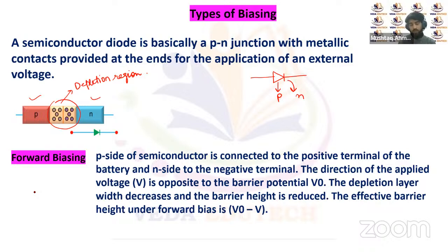Once the PN junction diode is forward biased, the potential barrier decreases continuously as we increase the biasing, till the height of the barrier is effectively reduced to zero. So if we connect a biasing at least equal to the barrier potential, the net potential at the junction of this diode will be equal to zero, or we can say the external biasing becomes equal to the barrier potential.